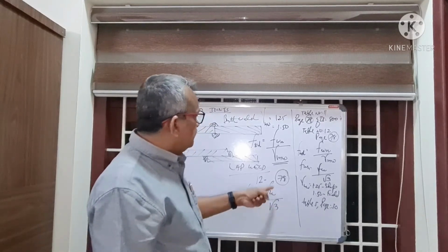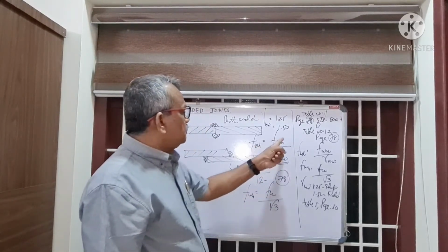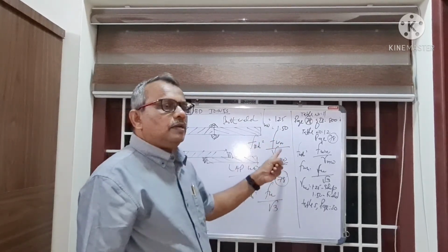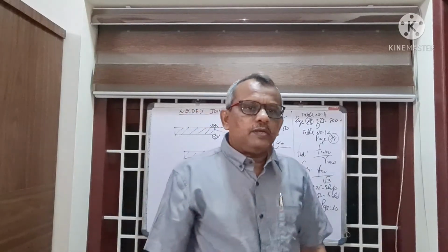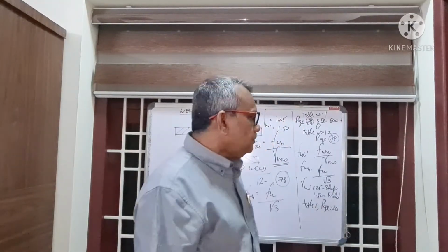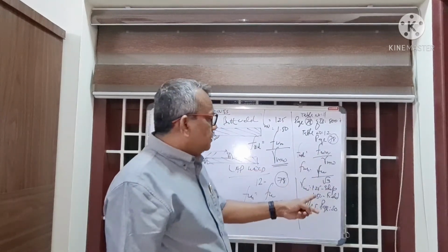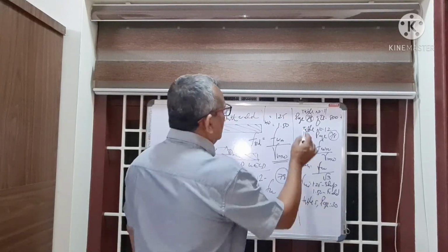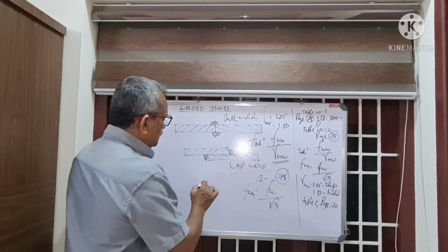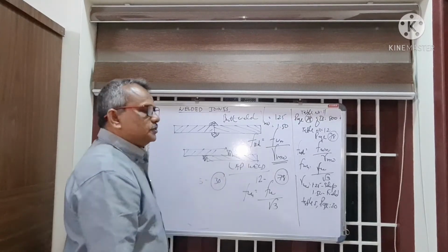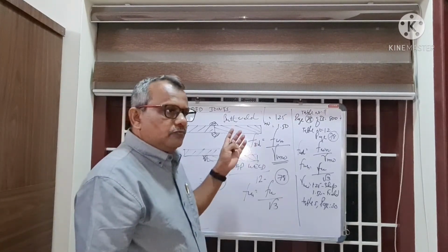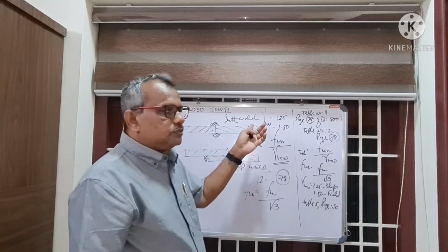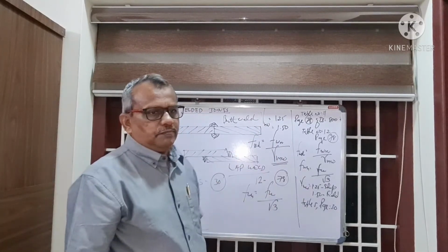So first find out this FWN using this equation, then substitute here FWD is equal to FWN by gamma MW, where gamma MW will be equal to 1.25 or 1.5 respectively, as in a workshop or in the field. Those values are also given in Table number 5, page 30. So you can refer to IS 800 to get the relations and also the values of the partial safety factor, as the case may be.